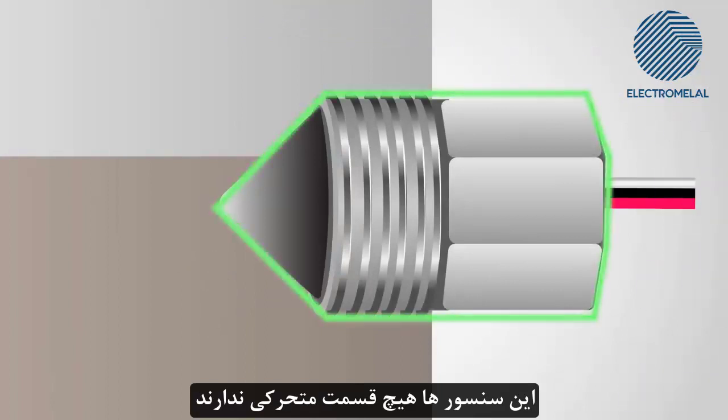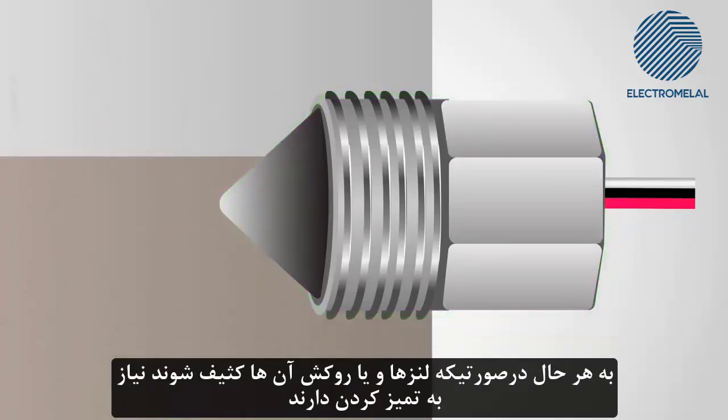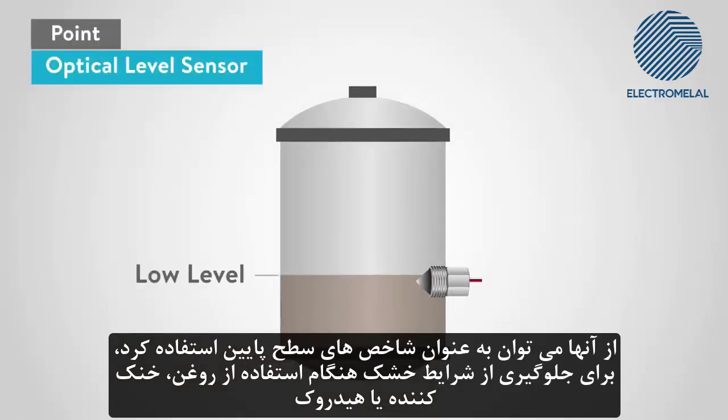These sensors have no moving parts. They are not affected by high pressure or temperature, are small in size, and can be used in liquid applications. However, if the lens gets coated or dirty, they would require cleaning. They can be used as low-level indicators to prevent run-dry conditions when using oil, coolant, or hydraulics.